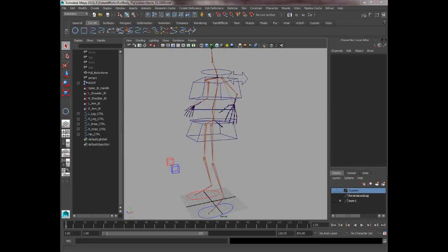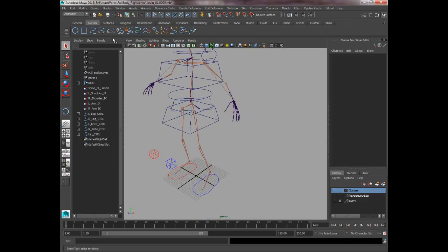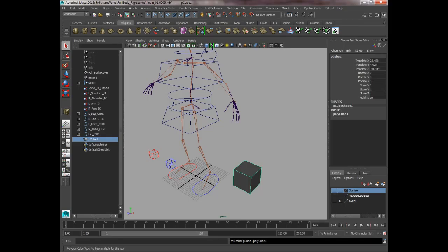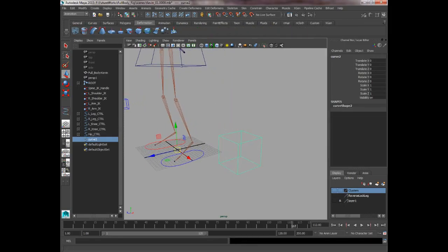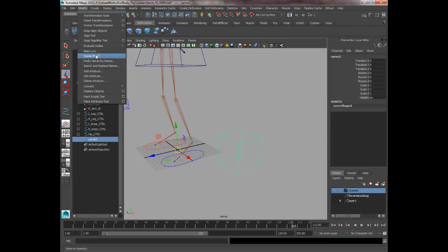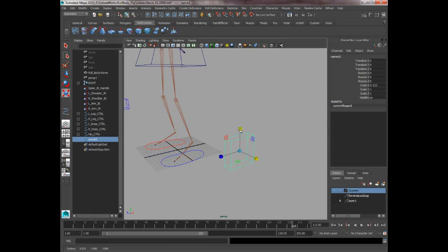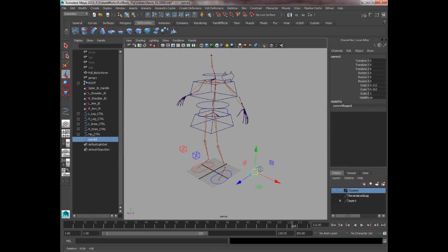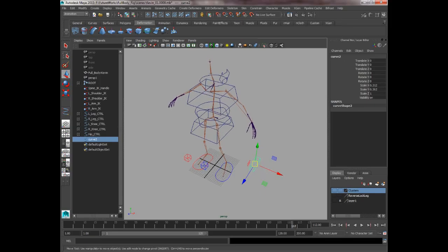Next we're going to be making the collarbone controls. So what I want you to do is make a cube again, a NURB cube using our polygon cube, making a control out of. Cool. And then what I want us to do is make a small little rectangle box like this. And I want you to drag and snap this to the arm joint, not the clavicle.